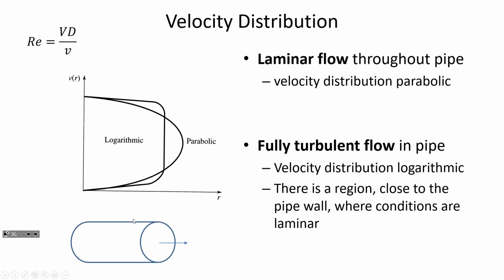which says that a viscous fluid can't have a frictionless movement over a surface that has roughness. That because of viscosity, the fluid will adhere with the same velocity as that stationary surface at the boundary between the two. And then the further away you get from the border of the pipe, the velocity goes up. So this figure is showing the velocity profile. A parabolic profile is characteristic of laminar flow, where the center of the pipe would have a velocity that's double the average velocity.